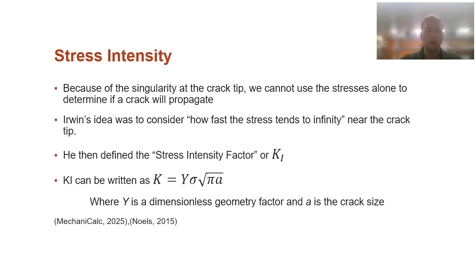And so essentially we have all of this stress building up at the crack tip, and it's going to be impossible to define what that stress is at the crack tip. So Irwin says, well, let's try to find how fast that stress is tending toward that infinity somewhere near the crack tip.